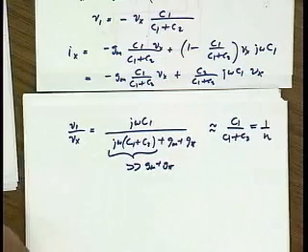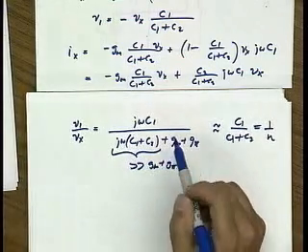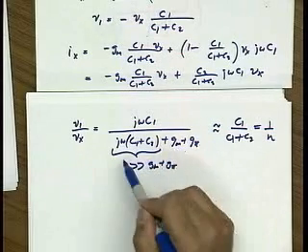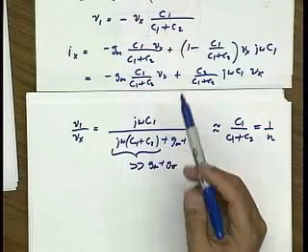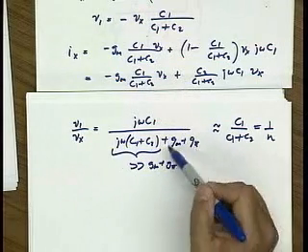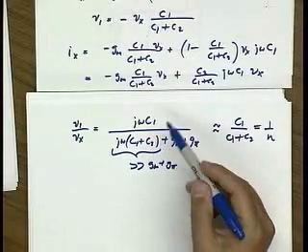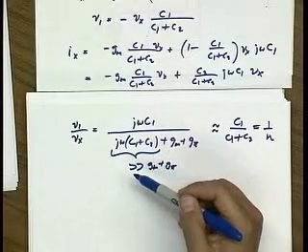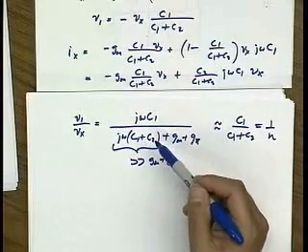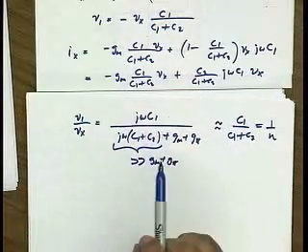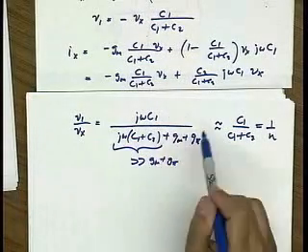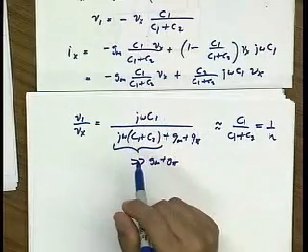Okay? So it's actually very important that this approximation hold, because you can see when this term dominates, this thing becomes real. In other words, the voltage feedback is actually real. If this term is important, then the voltage feedback is not purely real and there's a phase shift. And as you'll recall from the first couple lectures, if there's a phase shift in the feedback network, then the circuit will not oscillate at resonance. It'll oscillate off resonance in order to compensate for this phase shift. Okay?